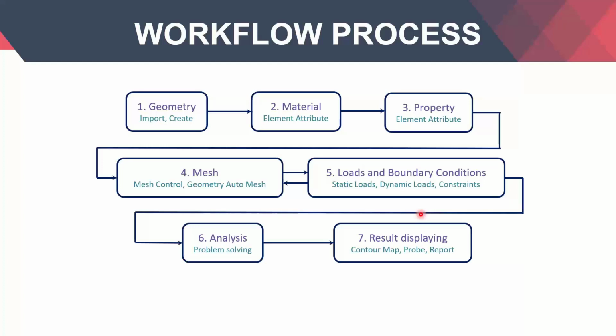And based on that, the flow of the horizontal stress path is what defines the orientation of the crosscuts and the main tunnels. Otherwise, if your main haulage road or your main tunnel or your main sublevel is perpendicular to the principal stress, then yes, you will expect major damages throughout the lifetime.